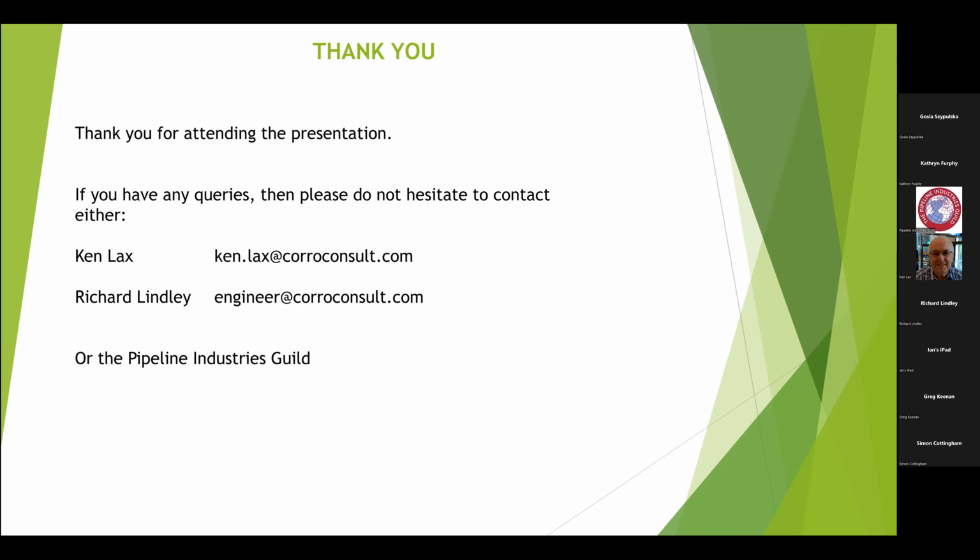Yes, thanks, Ian. That's a very good question. Yes and no. It depends whether or not it's coated or if it's just bare. If it's bare, that will represent an increased drain on the cathodic protection current system, and there may not be enough current to go around, in simplistic terms, to protect the other defects. So if you had a small coating defect half a meter away, that might not be protected because all the current's going to the big one.